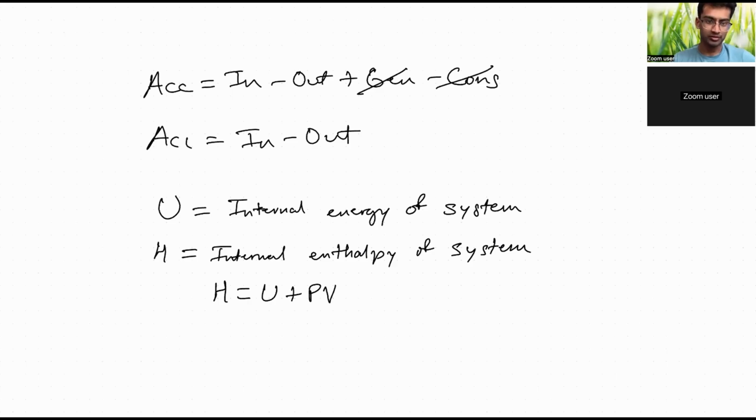So this is fluid work, PV. You can imagine this as flow work, right? This is the reason we make this distinction, so that we're going to have terms with U and terms with H, and it's important to know the difference between the two. So that's why that's there.